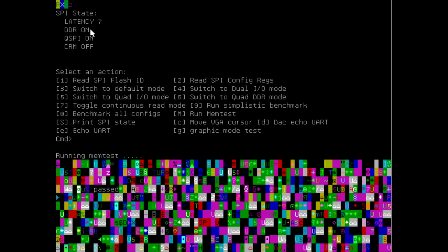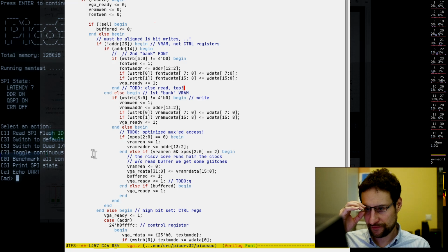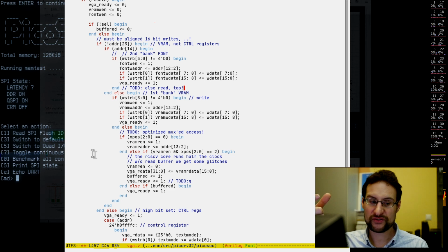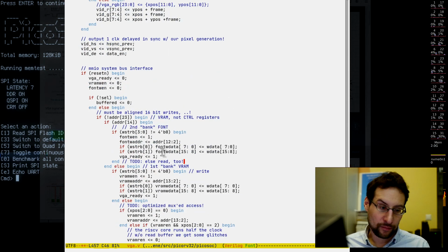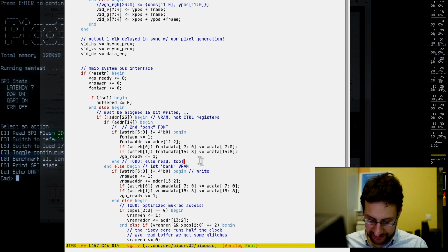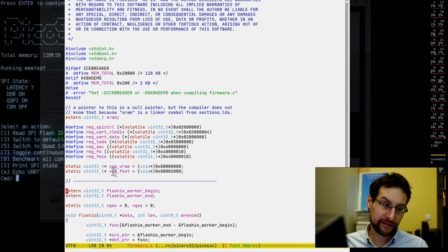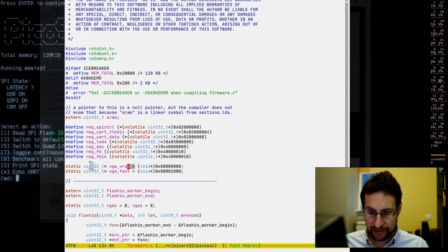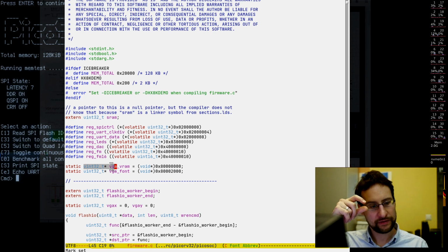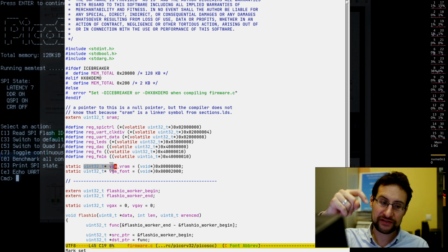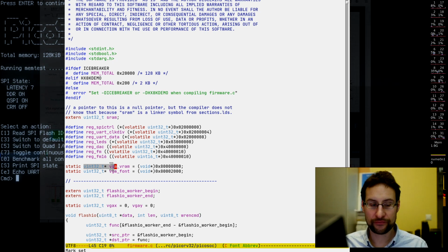And otherwise, the only thing that we could probably do better, and maybe do not even really cost too many more logic elements, is that right now the setup is a little bit funny: we have a 32-bit address space, but our VRAM is only 16-bit wide. And so we can optimize the performance quite a lot and even make programming a little bit nicer, because right now it's a little bit strange, a little bit non-standard, having 32-bit addresses, but right now we are throwing away half of them. So only every 16 bits is a valid address to read and write, for simplicity.